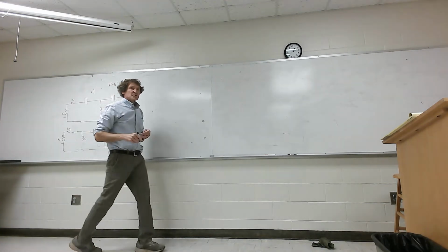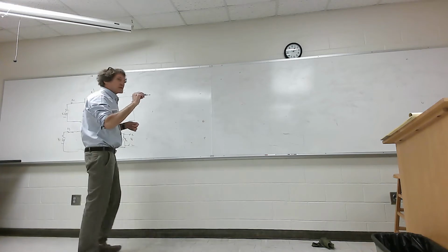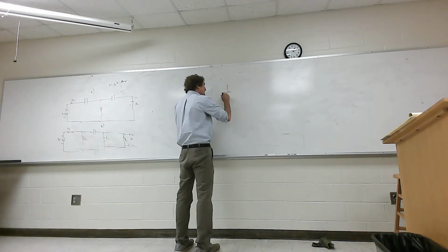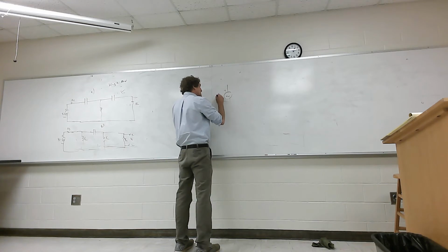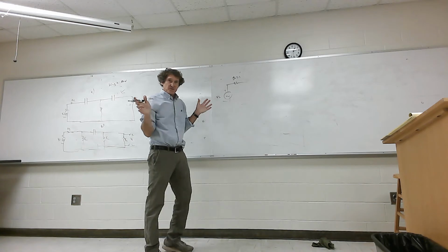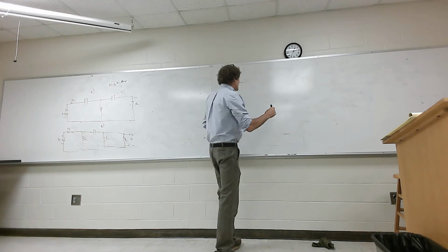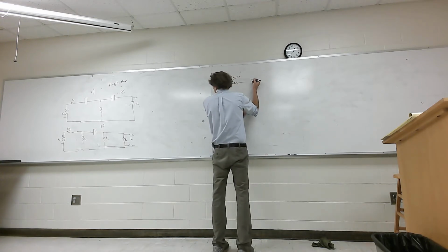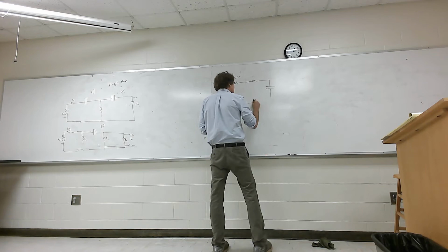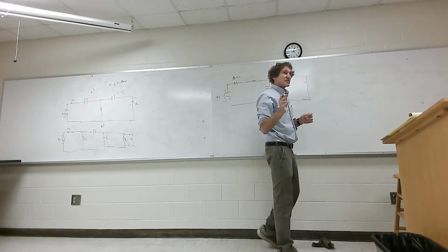So in his book, he says start with a low pass filter design. I'm going to start with this one, but it's going to be for a low pass filter. And the only thing I'm going to do is this. Just like he does in his book, this is Vs. I'm going to have some value G naught, which is going to be 1. It's just a normalization. You take the series resistance and divide it out, it becomes 1. And don't worry about that part. Now, here, this is going to be an inductor, and I'll get to that value in a second. This will be a capacitor, so I'm going to start with a low pass design and turn it into a high pass. Are you all with me on this class?